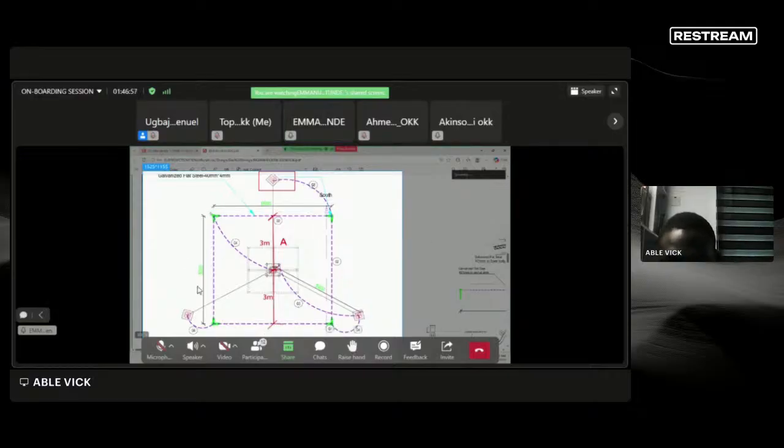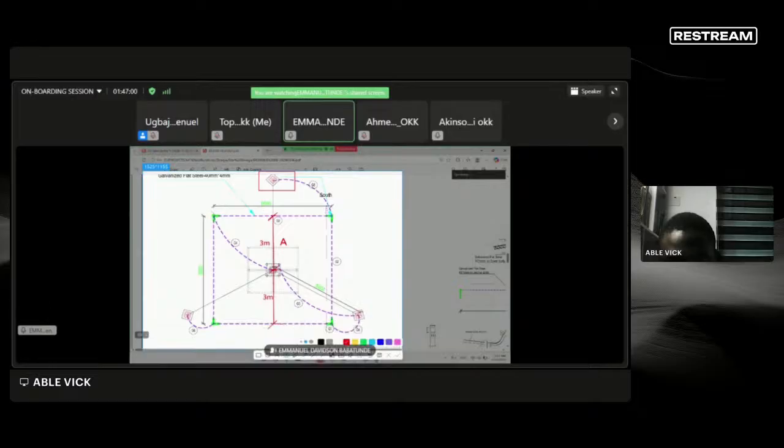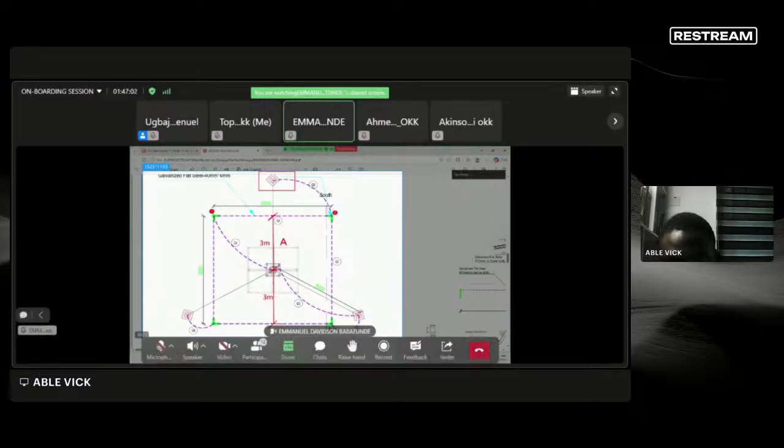So at each corner of the earthing ring of 6 by 6, you're having galvanized angle rods installed. At the 4 corners, you're having angle rods installed. Those angle rods should be driven into the ground. So after excavating 700 mm depth for your earthing around the 6 by 6 trench, install your earthing rod at the corners and drive them into the ground, 0.7 meter.